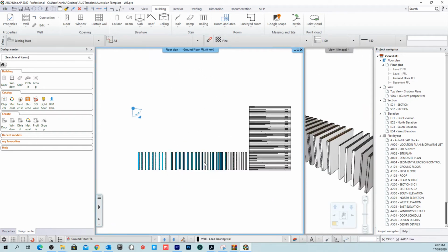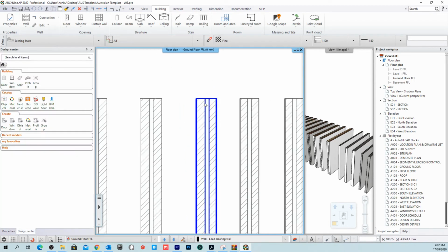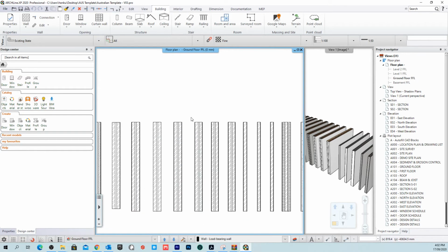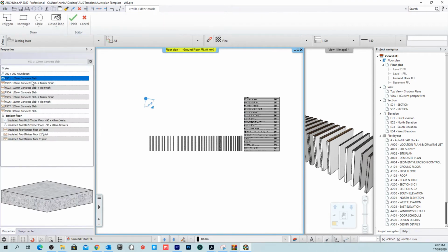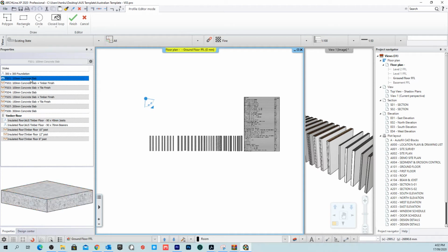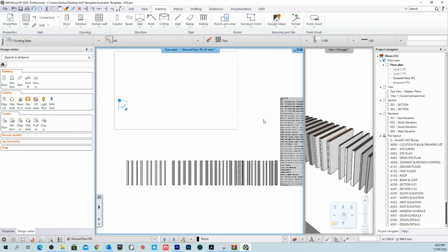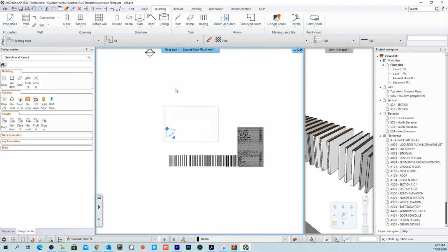So if you look at these, basically, each wall has a white fill that covers anything you see underneath. So nothing will be intersecting, right? And the same thing with slabs, right? So there's some slabs that we've added as well. So we've got concrete. You can add all these ones from the styles pack, but essentially, these have a fill that you can edit, right?